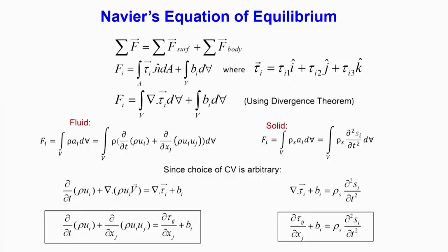Now, you can write that also in this bracket what we have written, because you can couple that with the continuity equation and then combine the terms together as a product rule of derivative, and then you get this form, which is the conservative form. It is important because in numerical methods we use the conservation principle. For analytical work we typically use the non-conservative form, which is just the total derivative in the original expression.